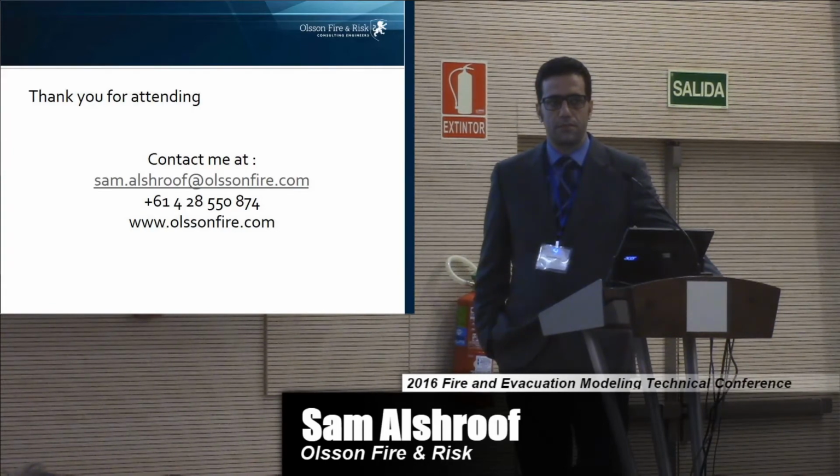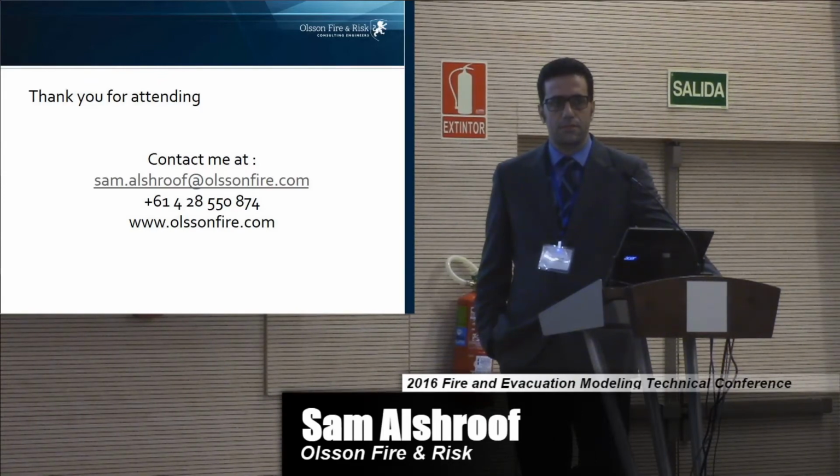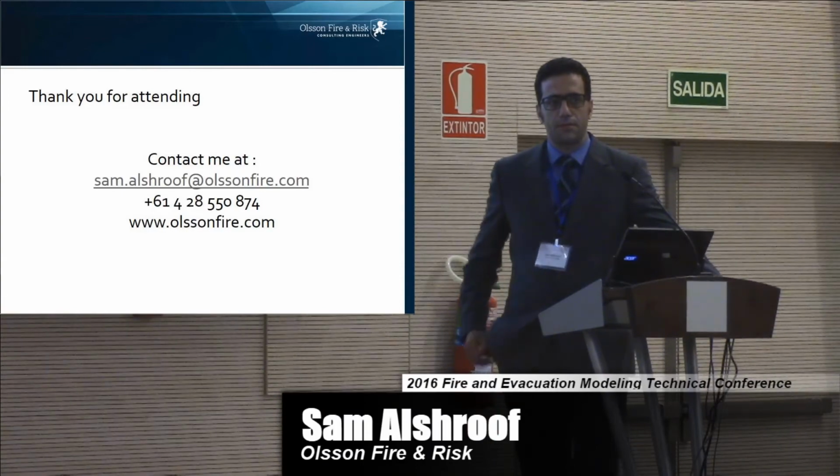We did our own proofs as well, and with that shroud method that I think Thunderhead published on the web, the JETFAN modeling is working much better, and it's quite correct even with coarser grids than it was before. I think it's mainly solved this problem.